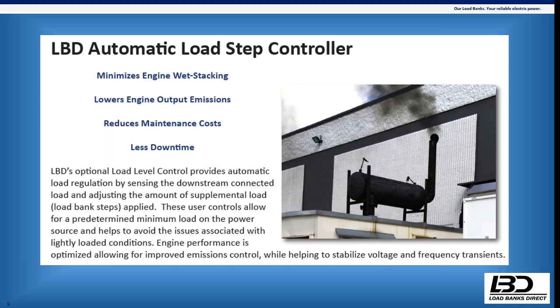But as a general rule of thumb, when that's in operation, it's keeping it loaded 30 to 50%, unless there's some other driving factor. If they want it more heavily loaded or less loaded, we can do that as well. But as a typical rule of thumb, we set them up to keep it loaded 30 to 50% when it's supplementing load.